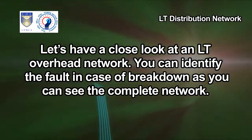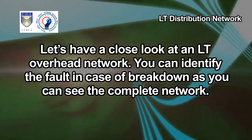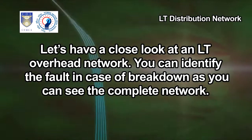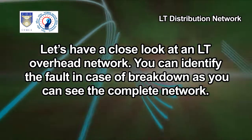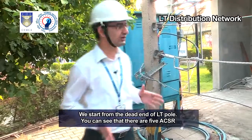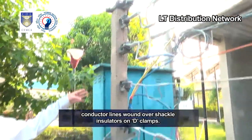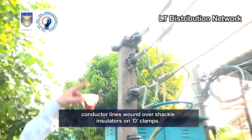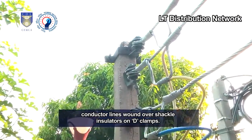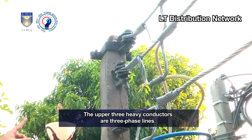Let's have a close look at an LT overhead network. You can identify the fault in case of breakdown as you can see the complete network. We start from the dead end of LT pole. You can see that there are 5 ACSR conductor lines wound over shackle insulators on D clamps. The upper 3 heavy conductors are 3-phase lines.